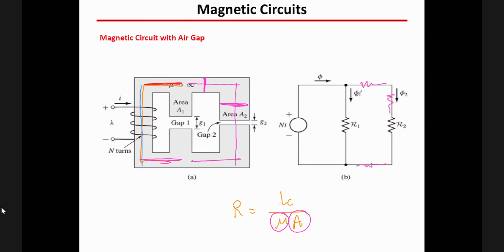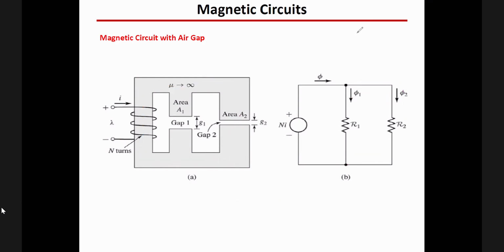We know that at the end you will combine all of them together, but it's a mistake to assume from the beginning that the cross-sectional area is the same. So whenever material is different, just separate them. Whenever cross-sectional area is different, just separate them. Clear? We're going to see, of course, more examples of the meaning of this.